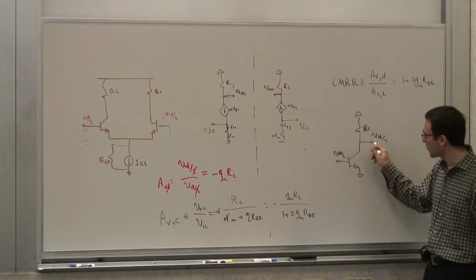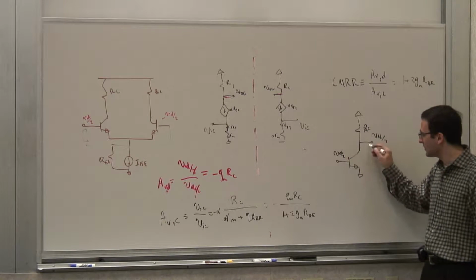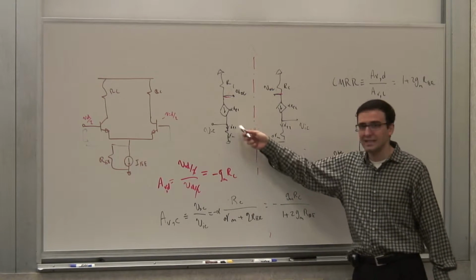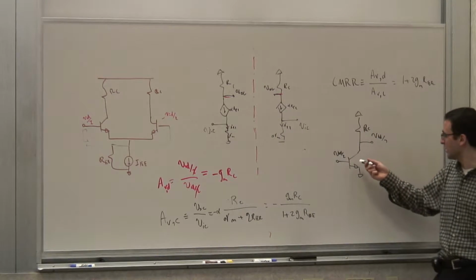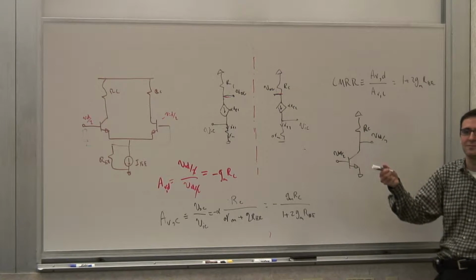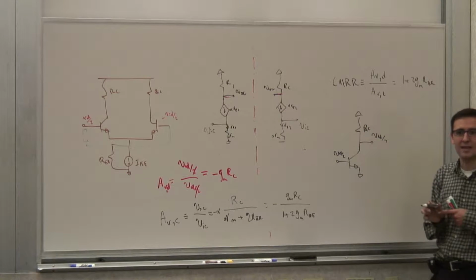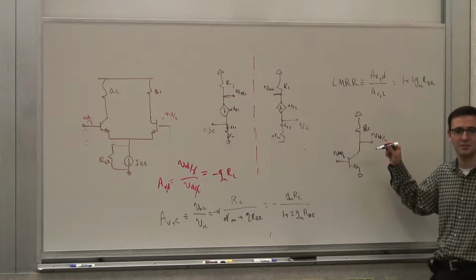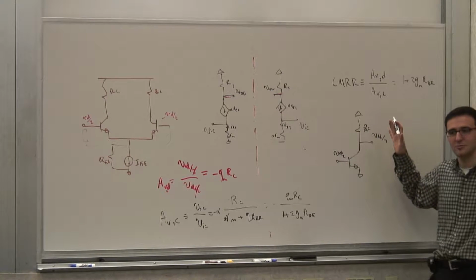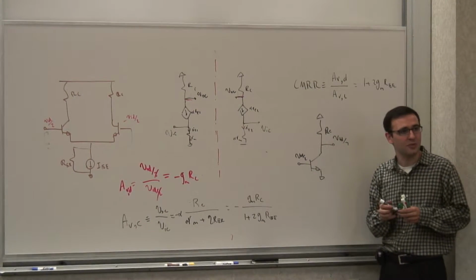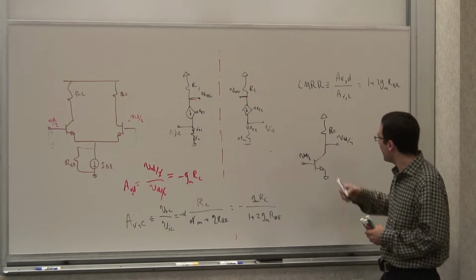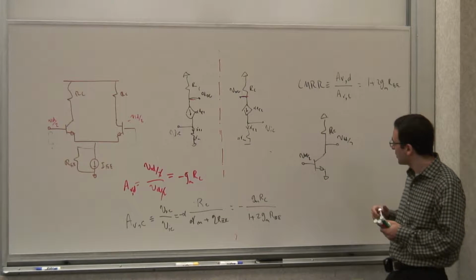When I draw it this way, what I mean is that I'm really looking at the small signal model. But I want to avoid drawing these things as much as I can. So I want you to, in your head, think of this transistor as that. You have to practice that. We'll do this multiple times. Otherwise, we'll have to redraw everything, and when we are talking about a 30 transistor circuit, we have to draw a really huge small signal model. You don't want to be doing that. Now, we have this relationship between VID and VOD, and that's the equivalent half circuit.